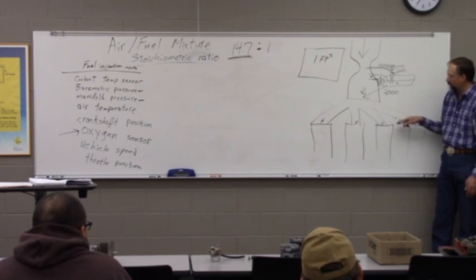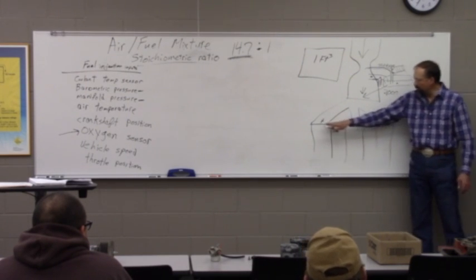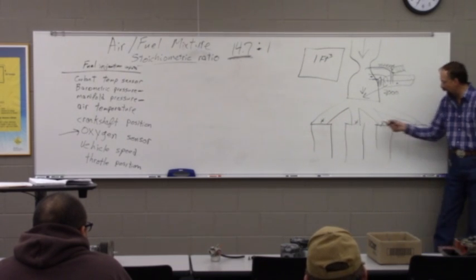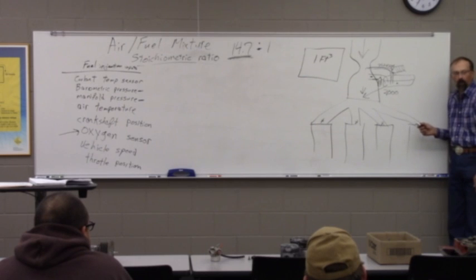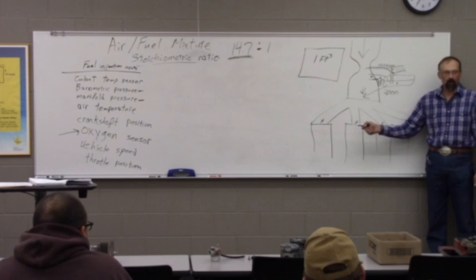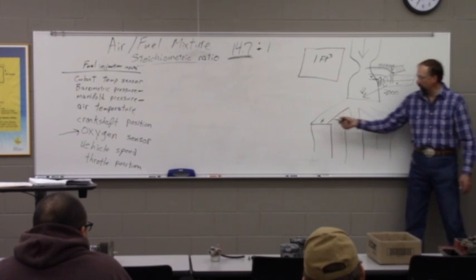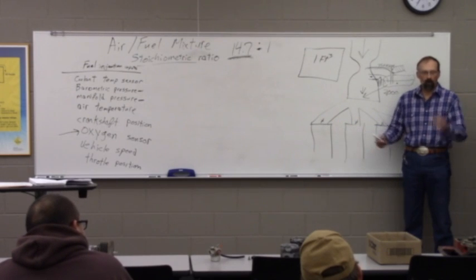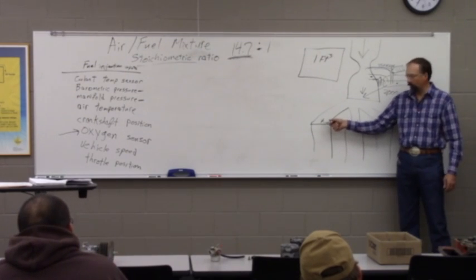And that turbulence actually helped to atomize the fuel, but it didn't necessarily help keep even fuel delivery to the different cylinders. And the same thing when they first started doing multi-port, putting all these injectors down here, the earlier multi-port systems, those injectors sprayed all the time. Well, last week we talked about how long our intake valve was open here.